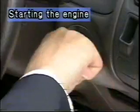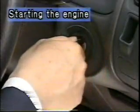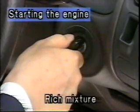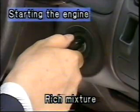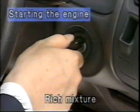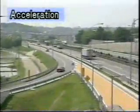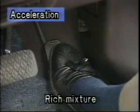Now let's look at different driving conditions, beginning from when the vehicle is started. Naturally, the engine is cold, making it harder for the fuel to be atomized. This alone is enough to create an improper air-fuel mixture. Hence, it is necessary to provide a greater ratio of fuel to air. Next, when the vehicle is accelerating, we know that fuel is heavier than air, so since the amount of air is increased when the accelerator pedal is pressed, the amount of fuel also must be increased to obtain sudden acceleration.